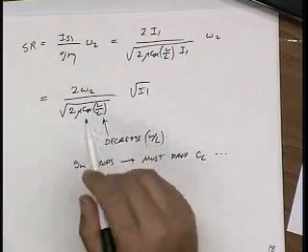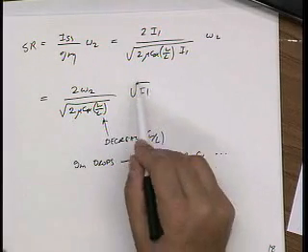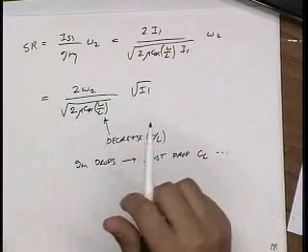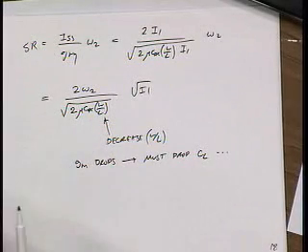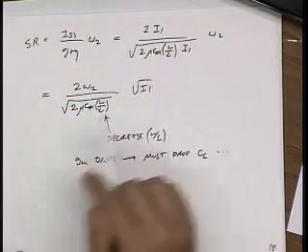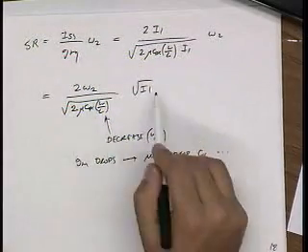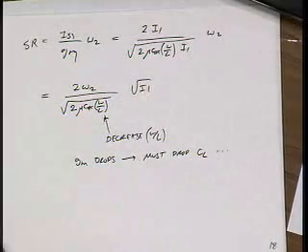I'll let you guys, because we have limited time here, think about this at home. Basically, let's say I fix my design parameters. I want to meet a certain gain, certain settling time. How can I improve my slew rate? It turns out you can by scaling I, but you have to think about it because you can't just change I without changing everything else, right?